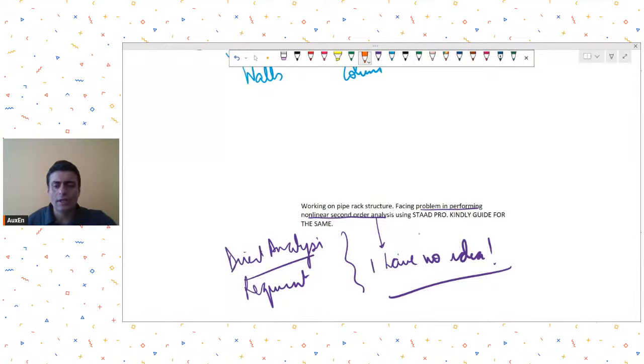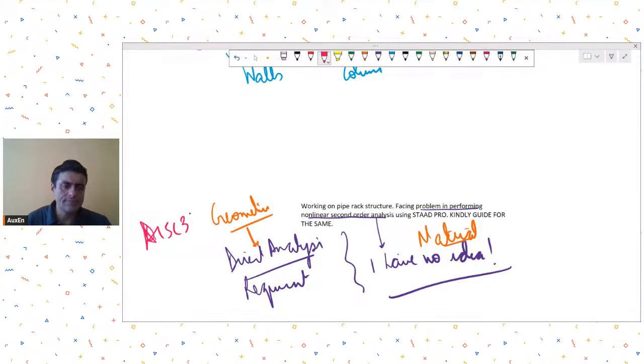Material nonlinearity, I have no idea. If you are asking about geometric nonlinearity, it is more like a direct analysis requirement given in AISC 360. The default method for analysis is the direct analysis as per AISC 360 Chapter C, design for stability.